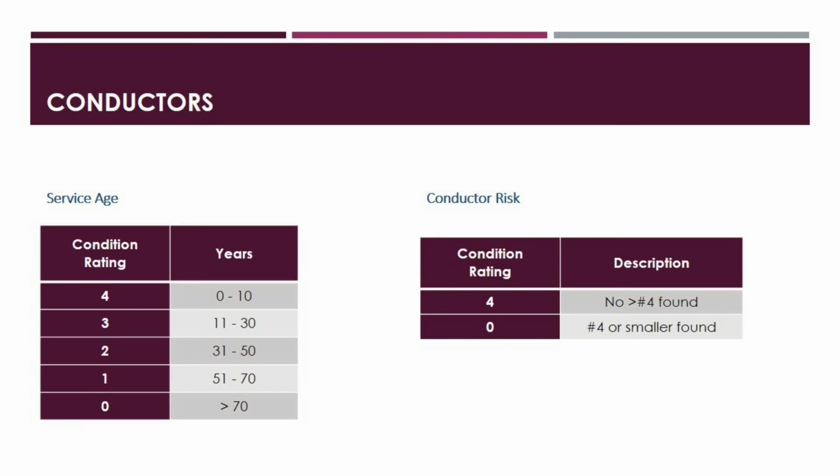However, due to the possibility of the conductor breaking, small conductors are frequently retired and replaced prematurely, and these are treated as a particular case in the health index algorithm, as I will be presenting to you. Now, the conductor health index methodology does not incorporate line section loading because it is anticipated that most lines are well built for future loading. So now let us look at the ratings in each category.